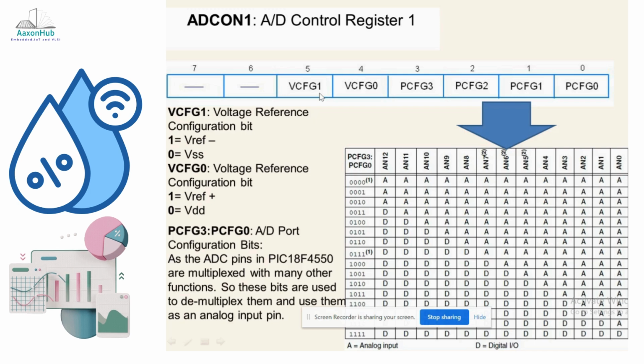conversion. Now in this architecture, as I have told you, sensors are of two categories. One can connect an analog sensor, or one can connect a digital sensor. So these 13 channels can act either as an analog channel or as a digital channel. Based upon your sensor category, whether it is analog or digital, you need to make the channel selection.